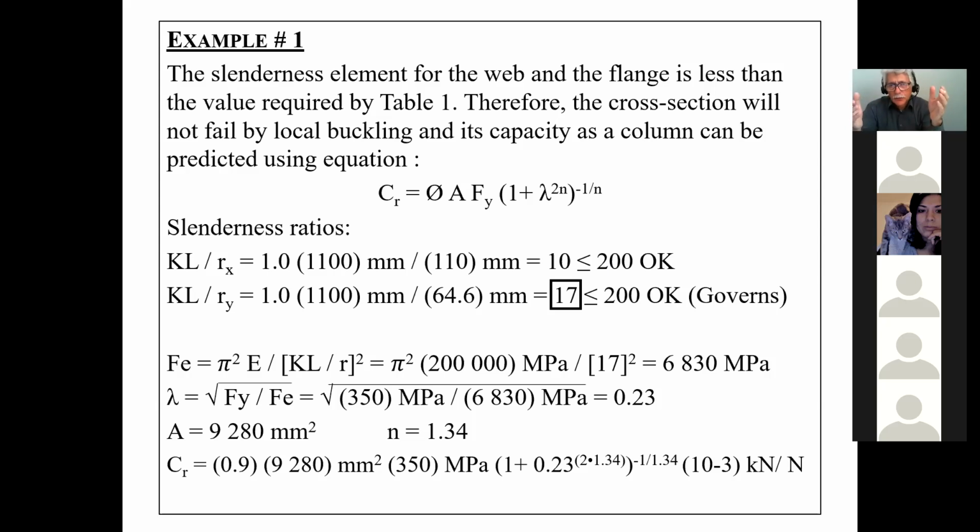You won't be able to work the steel. So any section you buy is rolled hot. All the W sections, the angles, the channels, they're all rolled hot. As far as the HSSs go, there are two ways of making HSS. One is you take a plate and you bend it, called cold form. In other words, the plate is cold and the machines just bend it, and then it gets welded along the seam. That's where you use 1.34. Then you have HSSs that get extruded, while hot. And because they're hot, there are fewer stresses, so you're allowed to use a slightly higher value of n.